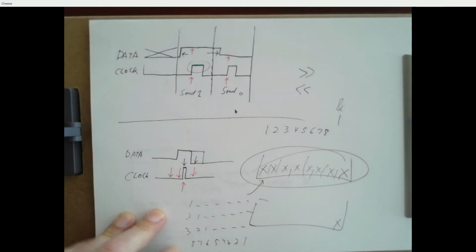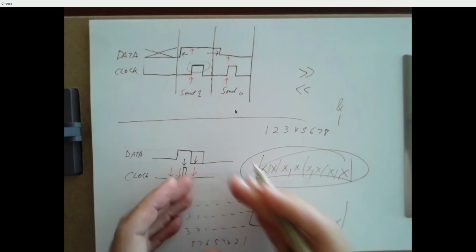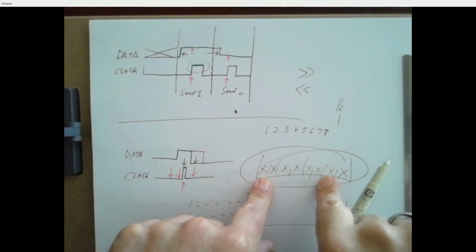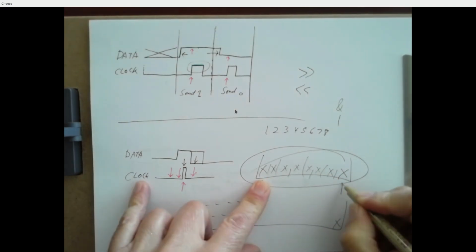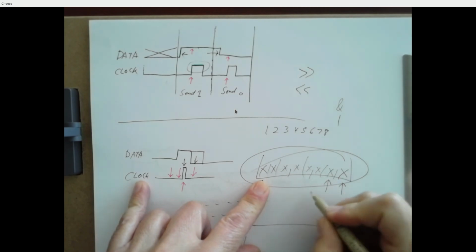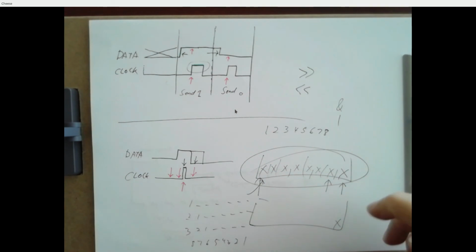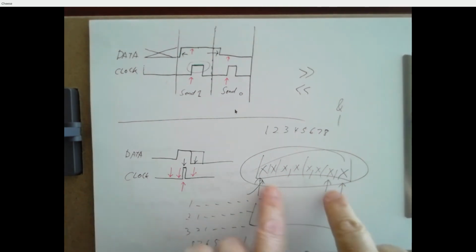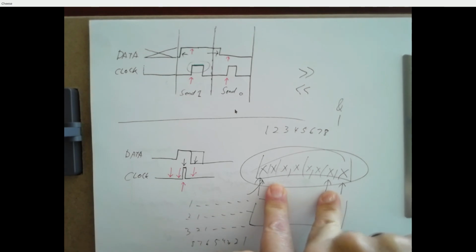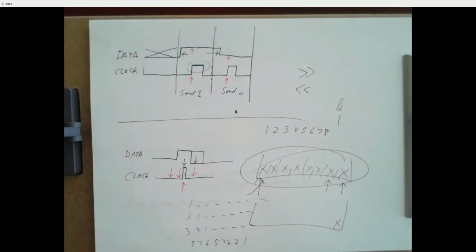The other option is take the bit that you receive, shift it to the left, and OR that with your character. So the first bit gets ORed right here, the second bit gets ORed right here, the eighth bit gets ORed right here. And I prefer doing that over shifting to the right, because shifting to the right with negatives, sometimes you get sign extension issues, but it's good stuff to mess with, right?